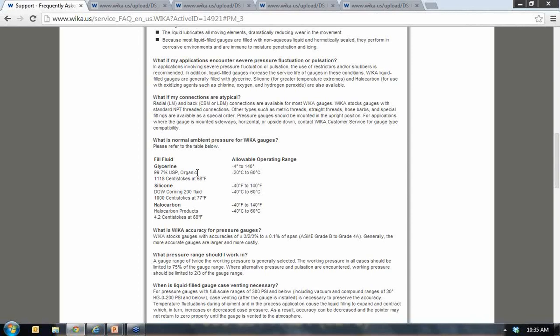Well, from an instrument longevity standpoint, that sounds like a perfect opportunity to separate the pressure gauge sensing element from the actual process fluids. I would say that putting in a diaphragm seal, which would give you a much larger surface area for the diaphragm to interact with the media, would prevent the freezing of the moisture in the lines from affecting the measuring element. If the issue at hand is something different than that, I'd be happy to research it more, but I anticipate that's probably what the question is.